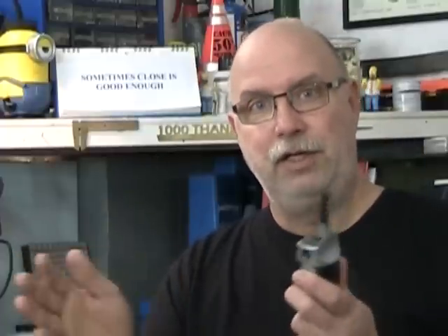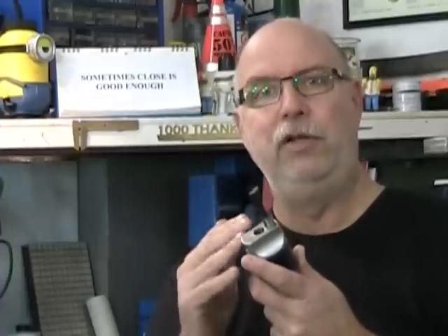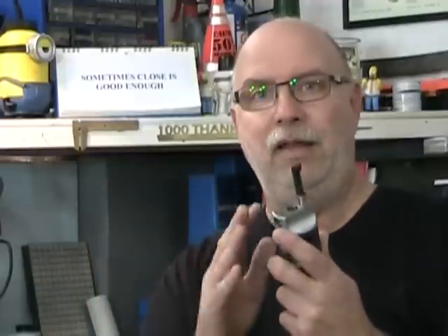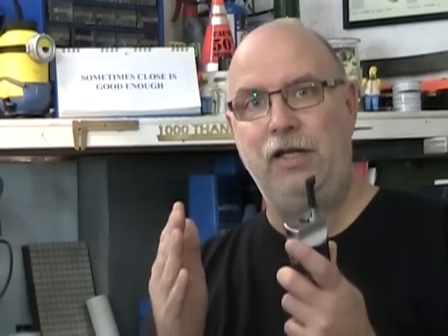And if your mill is good and square and your positioning of the table is good and accurate, well, you'll position a hole quite accurately. And what does that mean? That means that you're going to pre-drill a hole before you use this. The pre-drilled hole might be 1/1000th or 2 out in any direction, but when you bore to finish that hole, you will bring it back to its proper center position. So we have boring heads with boring bars. And on the lathe, we can dispense with the boring head and go straight to a boring bar. And if your lathe is good and straight and your part is turning concentric in the way that it should, well, you will be able to bore out an accurately positioned hole on the lathe.